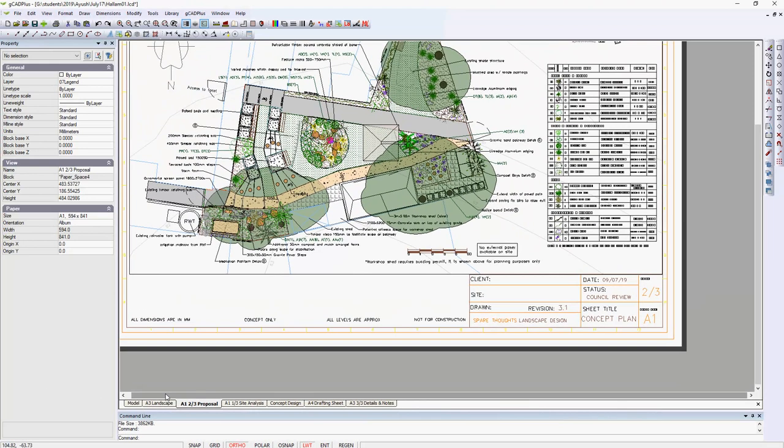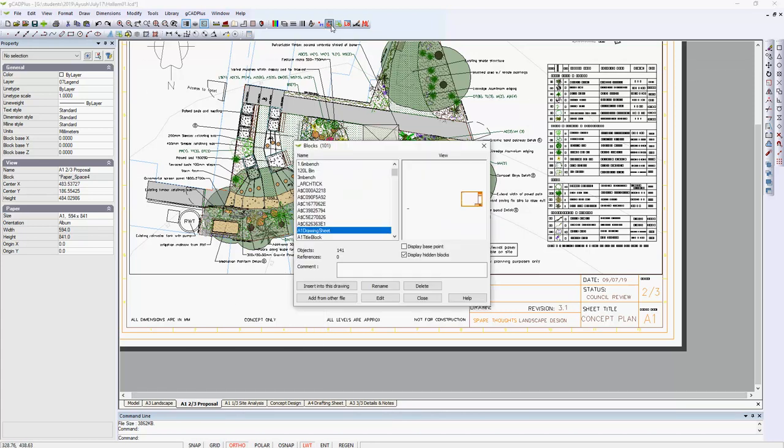And that's a relatively large drawing, and I wonder if, when I start working on this drawing, it wouldn't be a good idea to go into blocks, activate the blocks command, and just see what blocks are in the drawing. Notice lots of blocks starting with A dollar, C dollar. I'm not a fan of having those. They've come, I suspect, from an AutoCAD drawing, but I digress.